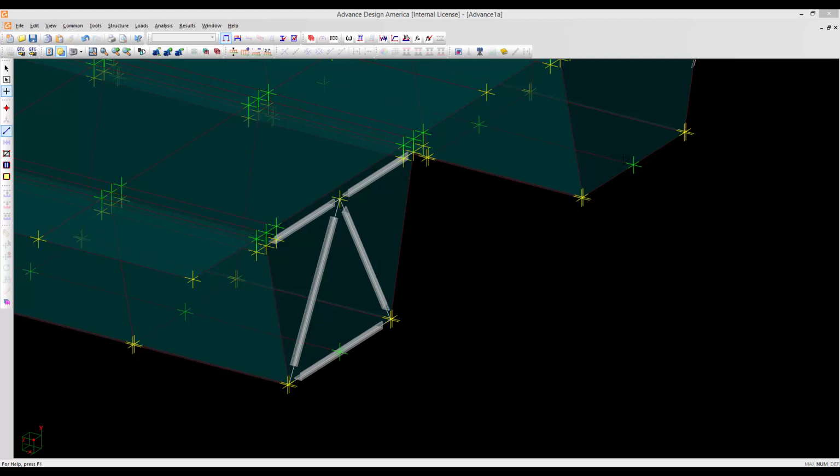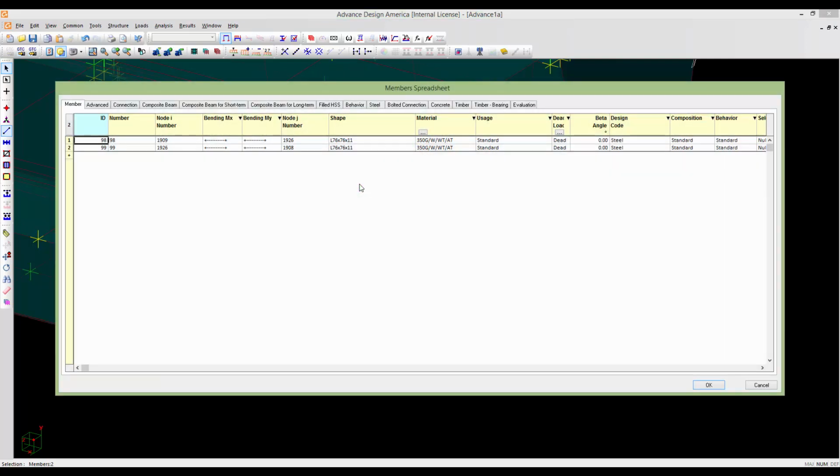We can always use the copy and paste option to copy to other girders. For example, if I want to modify one of the members here or two of them, we need to go to selection, member, and select these with holding control, and after that control H to modify the material or end conditions or other kinds.